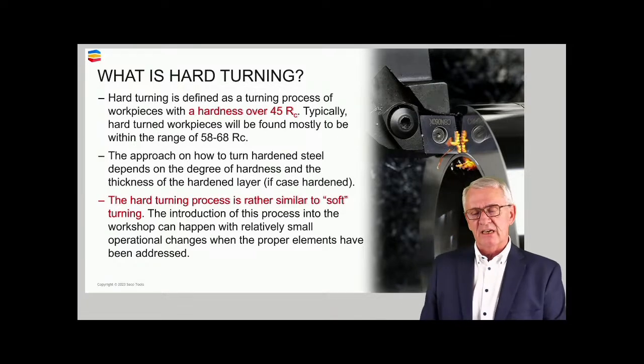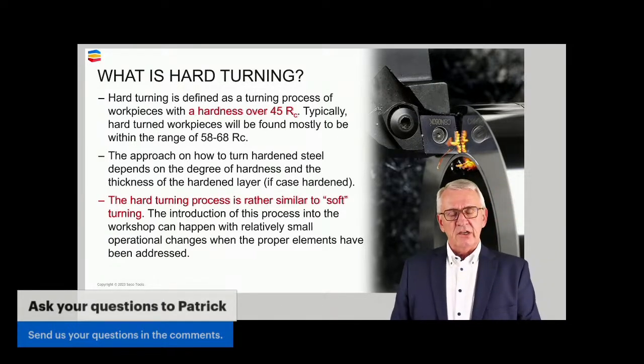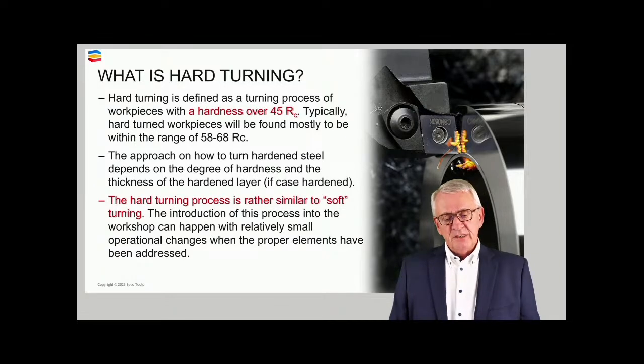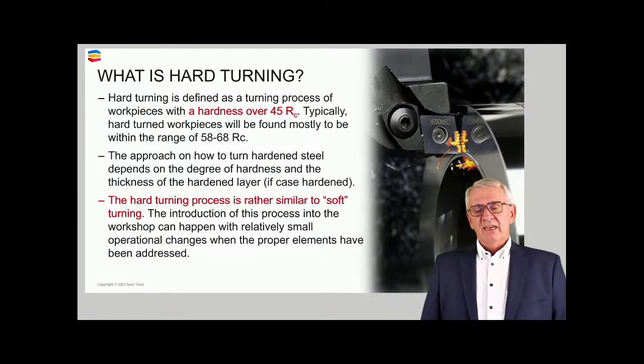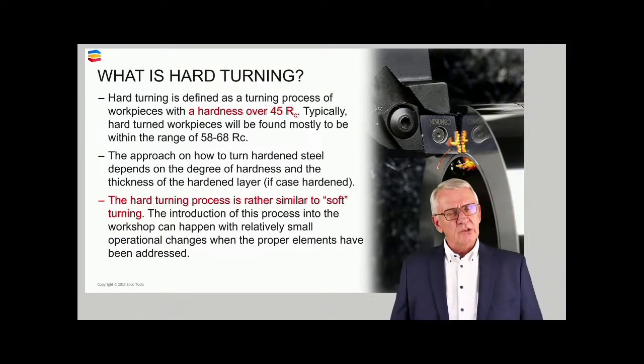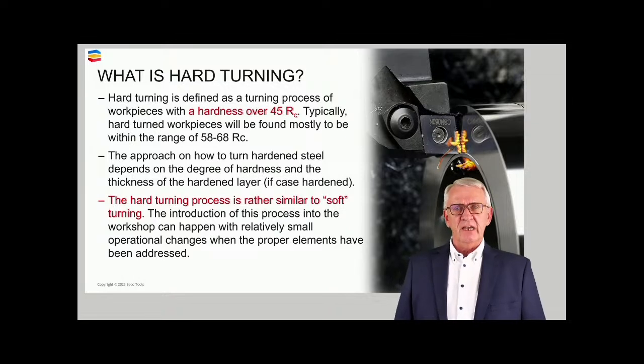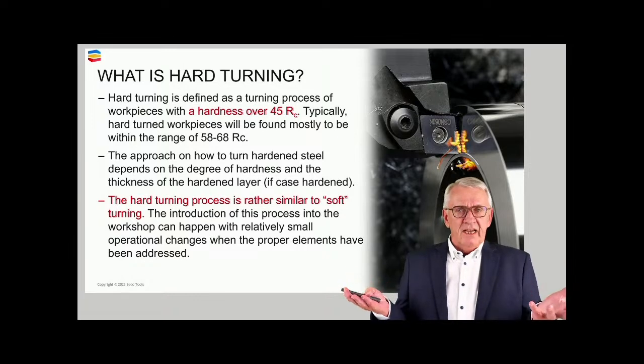Above 300 Brinell hardness, and from where the 300 Brinell? Well, that came from empirical data, from doing and observing. Above 300 Brinell, we saw things were changing. We saw that cutting forces and how they develop, heat and temperatures during machining, and structural changes in workpiece materials. We slowly slipped into a different situation, but still rather handleable.